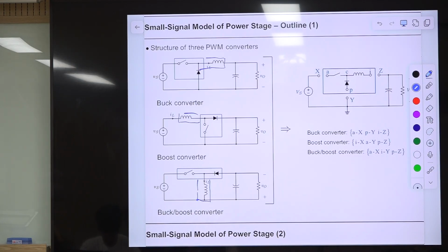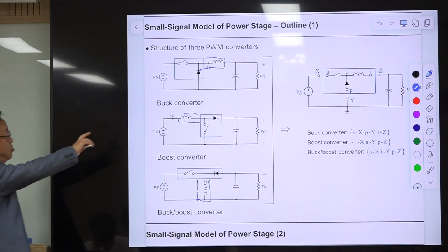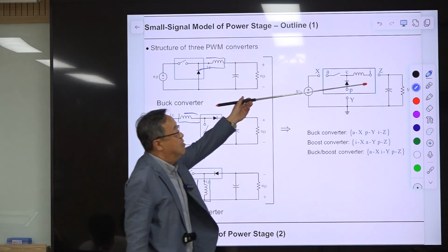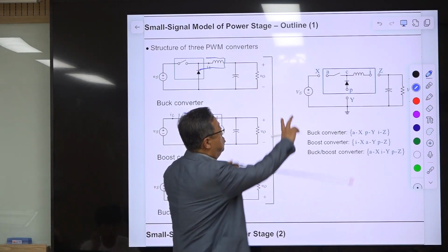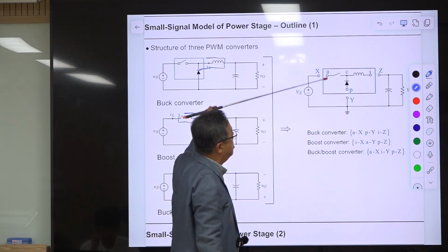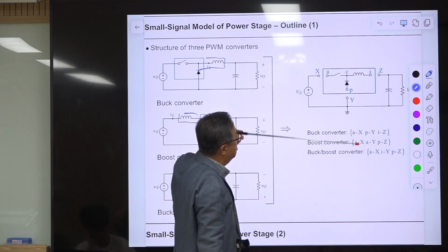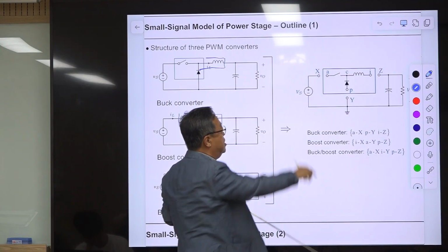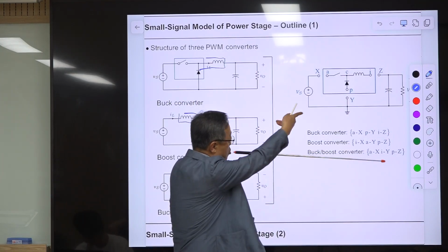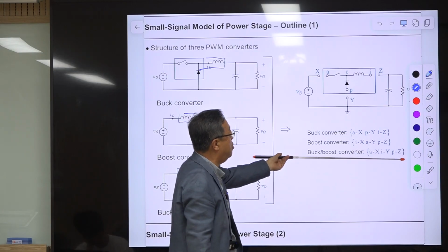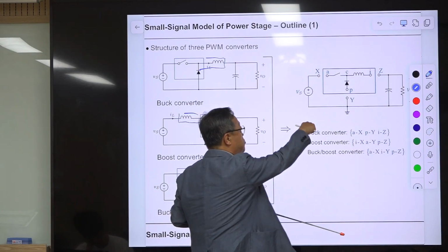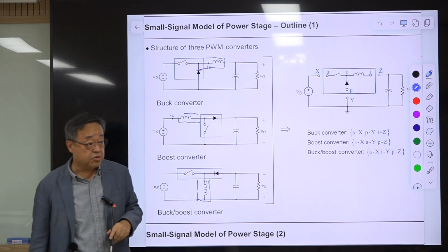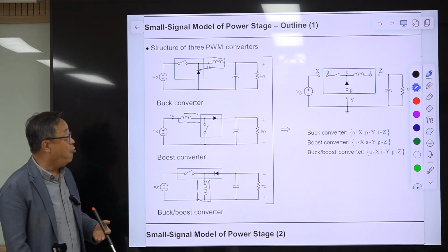This is called the three-terminal device. And this is the general layout. You rotate this, and with this connection like this, it becomes a buck converter. And if you rotate 120 degrees, it becomes a boost converter. Another rotation is a buck boost converter. Another rotation comes back to the buck converter. Okay, just rotating this. Right.